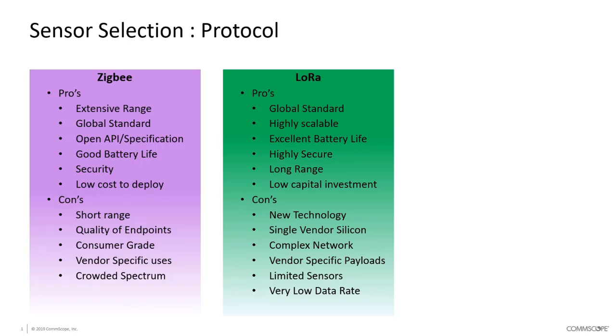And it is really a very, very low data rate because of the range and because of the types of application and because of the battery life that a LoRa network has been designed for. You see that the data rate itself is designed to be very low, a few bytes, and also you have shared time on the air, which means that you can't send large quantities of data, messages, or stream any kind of content.